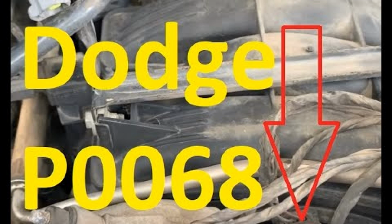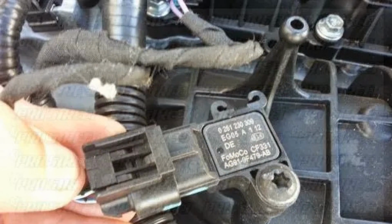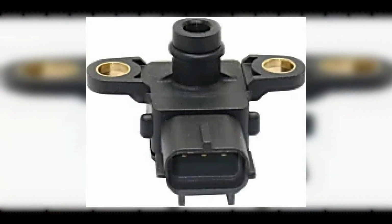The criteria for this code vary from one OEM to another, but to calculate an expected airflow, the GM algorithm uses throttle position, TP, barometric pressure, baro, manifold absolute pressure, MAP, intake air temperature, IAT, and engine speed. Mass airflow, manifold absolute pressure and throttle position sensors provide the rationality control inputs, but there are 4 distinct algorithm models on 2017 GM vehicles. How these algorithms are calculated is not as important as developing an understanding of what rationality checks are, especially when examining data from the live analysis tool.